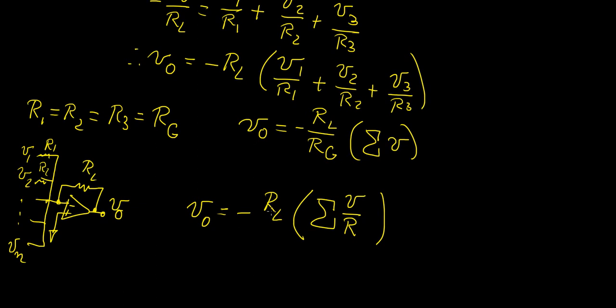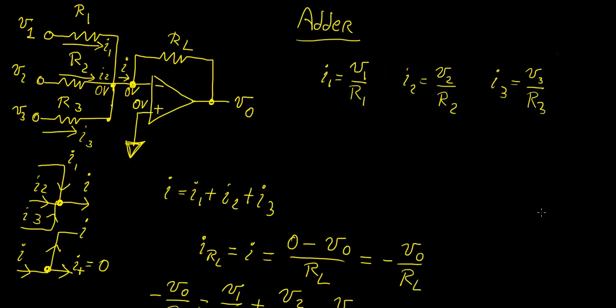And you notice that one of the characteristics of this type of amplifier is that the output is also inverted. So that means that the signal is basically going to flip around because it is negative. But it is a very important thing, and we're actually going to make use of this in later videos. It's a very, very neat way of performing addition of input signals. So if you imagine the way that a calculator would normally add numbers together in a digital way, this is kind of how you would add things in an analog way by using resistors and all those types of components.